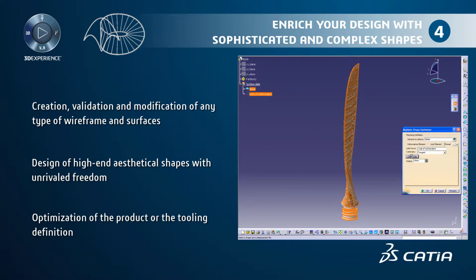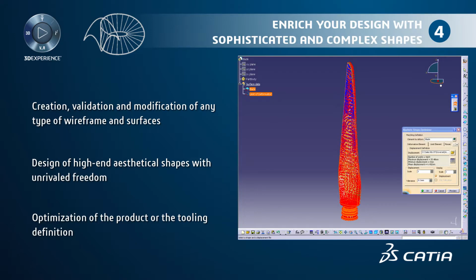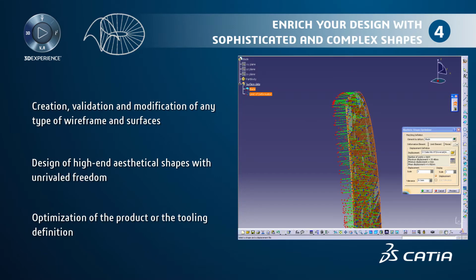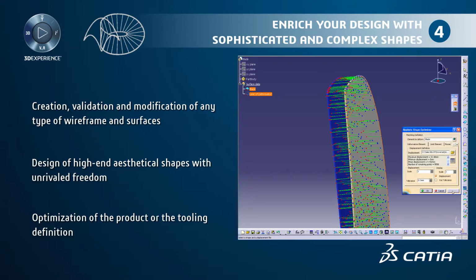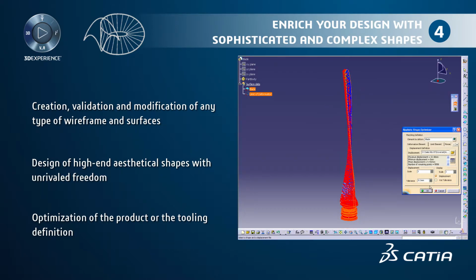And second, with Catia Realistic Shape Optimizer that enables you to morph an existing shape to match a given target. This target can be, for instance, computed by a finite element analysis system. This example of the helix of an airplane shows you the application of all deformations along a surface. You can check the displacements and even tune some computation parameters. Comparing the two parts, you can see that the deformation has been applied harmoniously and the surface quality of the original model has been preserved.